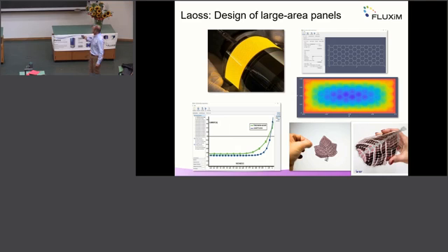Usually what we do to compare is input the properties of a very small solar cell, so it would be this blue curve with a nice fill factor and a nice photocurrent. But if the solar cell is getting large and the transparent electrode is not ideally conducting, then we lose in fill factor. That's the gap we want to minimize, from the small cell JV to the big cell JV. There is a gap in fill factor and efficiency.